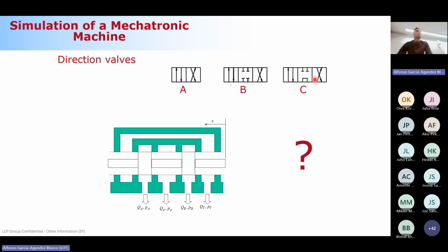Why not the third one? This is very important. Because, guys, in this representation, in the valve center, you would have a connection between these two ports, okay? This U would represent a connection between two ports. And in the valves, when the spool is centered, you don't have any communication, okay? That is the reason why this is not the one. There is a question.